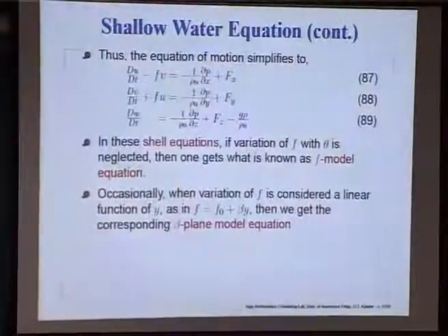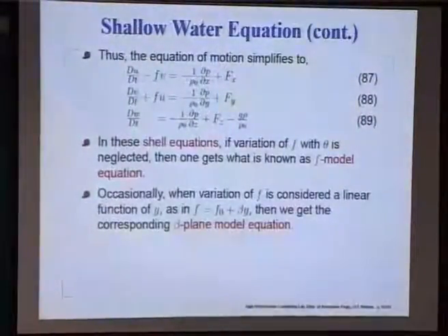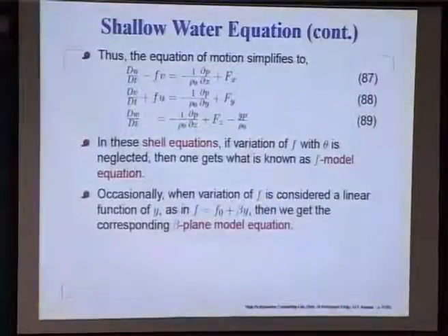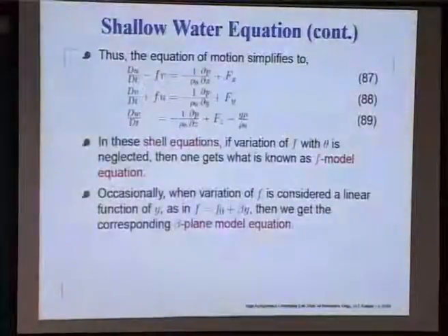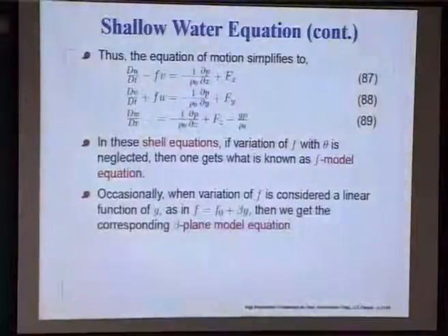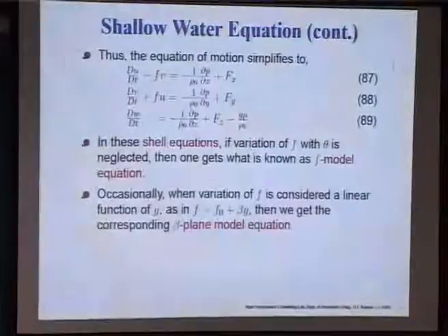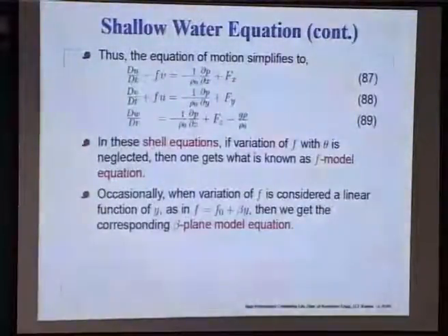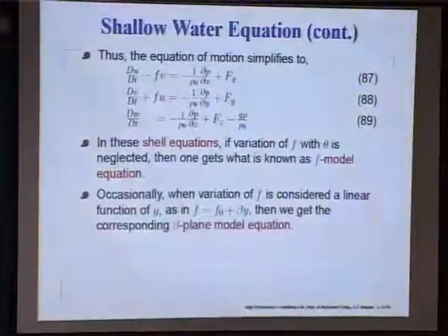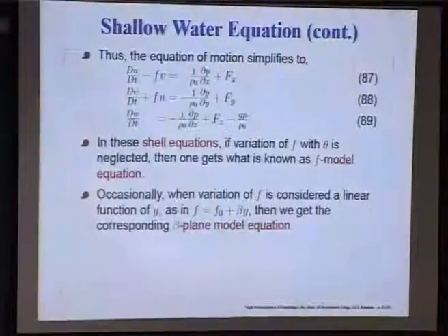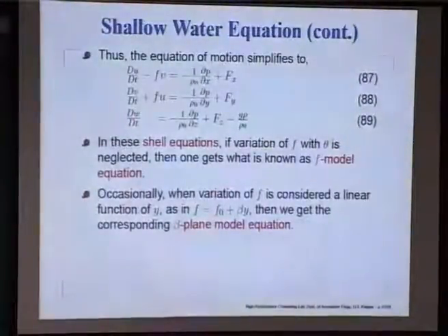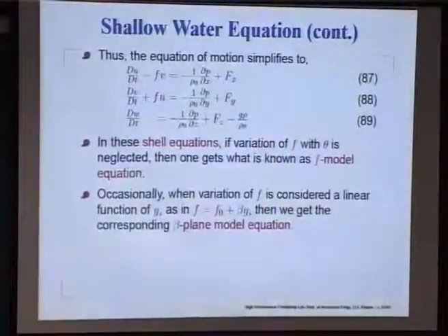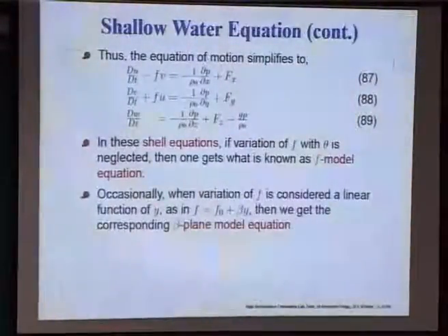Now, then what we could do is that we could write down the equations of motion in this particular fashion. So, this is the substantive derivative in the x, y and z direction. To that we have added those Coriolis terms in the x and y. In the z it is negligible, whereas these are the pressure gradient term which is driving the flow, and f x and f y are the bottom friction term that we have modeled. Okay.